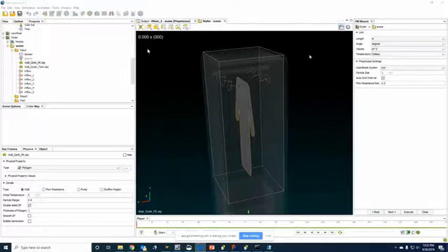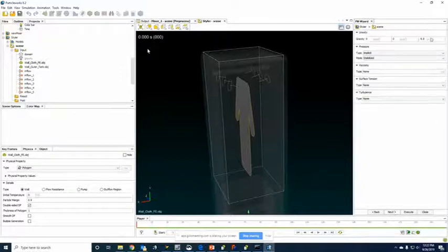And so if you click that next button, you're ready to change the particle size. So in this case, we're going to have a particle size of 0.01. So you'll set that for each model in particular. You'll have a single particle size, and go ahead and click next to go to the next step. Right now, gravity is set in the negative Z direction. We're going to go ahead and change that to the negative Y direction.